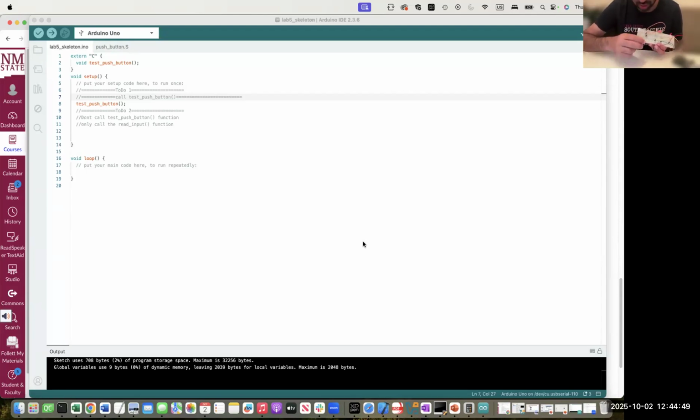Now I want to figure out, I have connected one leg of the push button with the ground. The function which I have enabled is this: if I provide an input of 0, all the LEDs will glow on, right? Now remember that on the other side there are two legs.